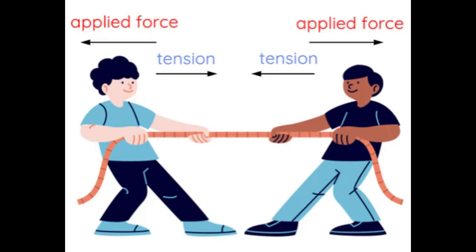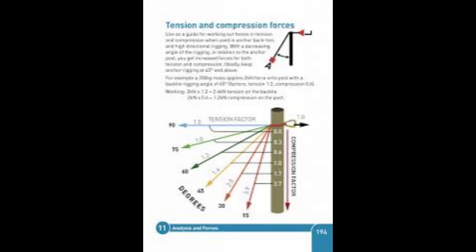The amount of tension is basically the weight of the object you're supporting, plus any extra push or pull from acceleration. If your load is just hanging there at rest, the tension in the rope equals the weight of the load. And because tension acts equally and oppositely along the rope, that's why we sometimes call ropes and similar equipment tension members. Tension isn't always just a straight line. You can have forces applied in multiple directions at once. Your system is constantly juggling vectors.